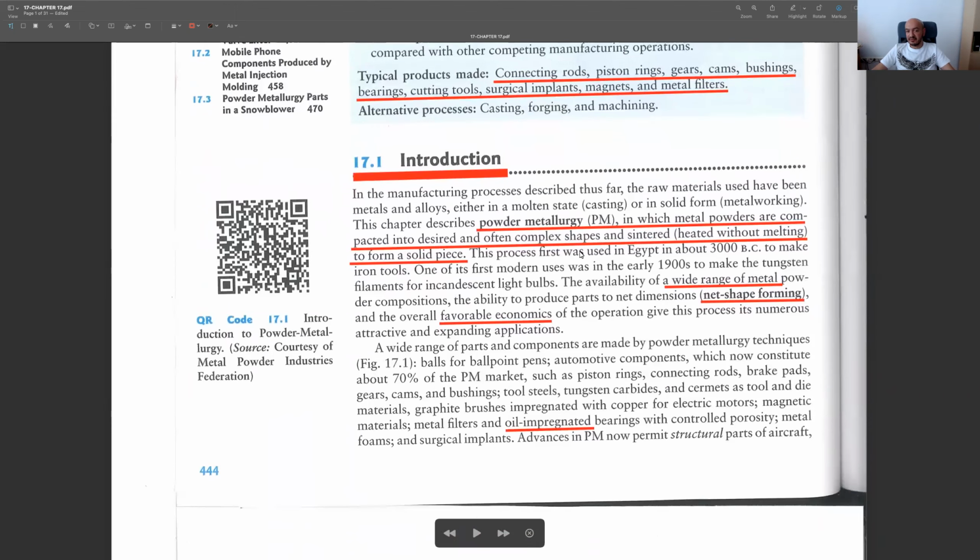So what we are doing in this basic process, as the name implies, we are using metal powders. We put them into a kind of die. We compact them. Depending on the complexity of the die, the resulting shapes may have higher geometric complexity. Later, after this compaction is over, we take this part out and do extra operations like sintering. With the help of it, the strength of the part is increased. And lastly, if it's required, you may do some extra secondary operations.